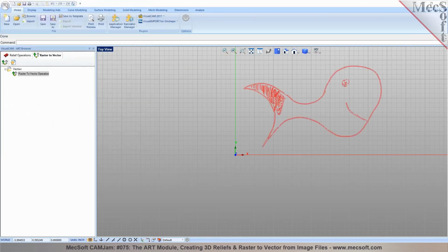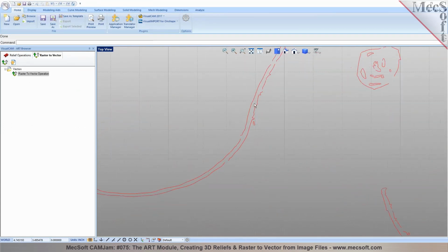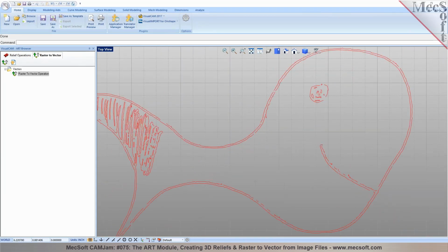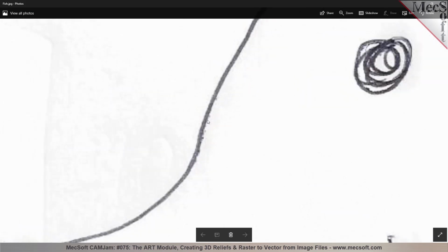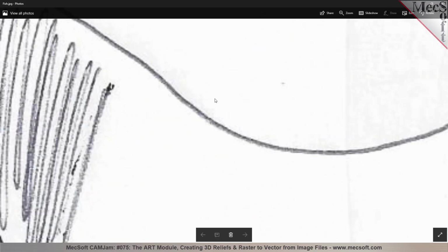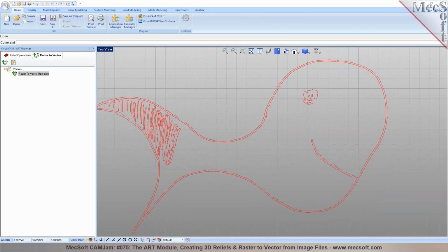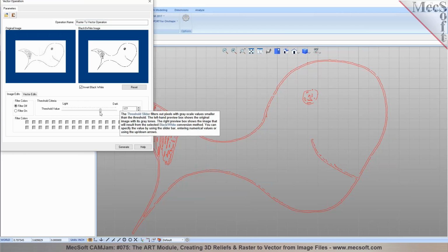So in this process, it's taking the image and converting it to a vector geometry. So based on the image what you have, it shows all of these noises in here. Do you notice that? Yeah. So if you take a look at the image, you're seeing those noises from the image. Okay. So it's mapping it to the closest pixel that you have on it. Right, so if you go back in here and you change the threshold, I can go back and edit this. If I reduce the threshold, the less amount of information you're going to see. Or if you increase the threshold, you'll see more noises on the image.